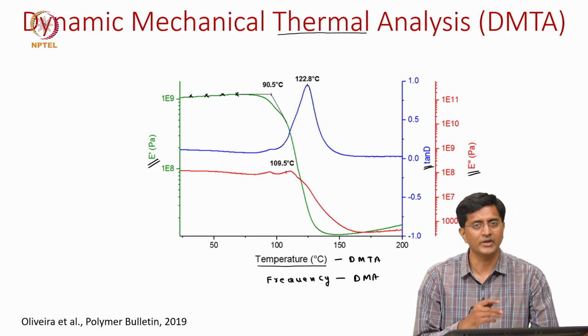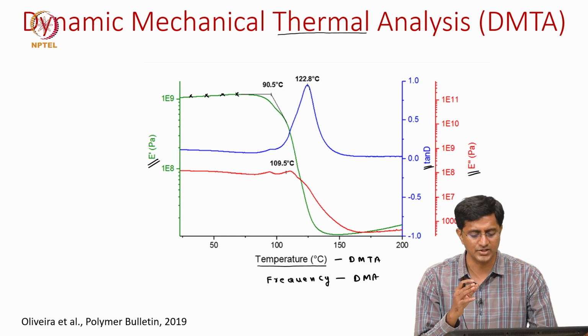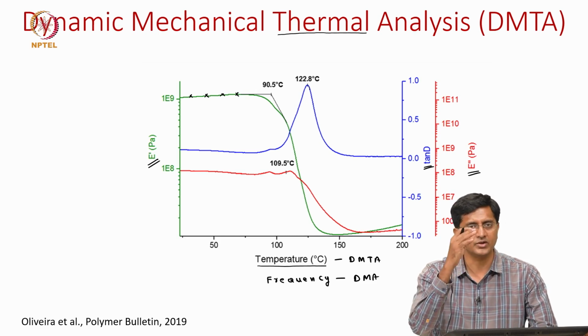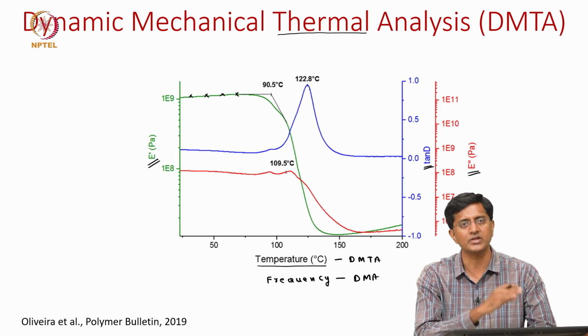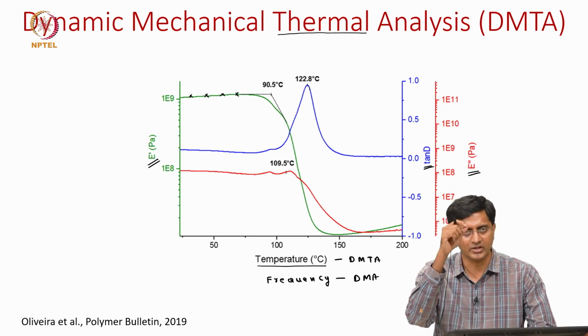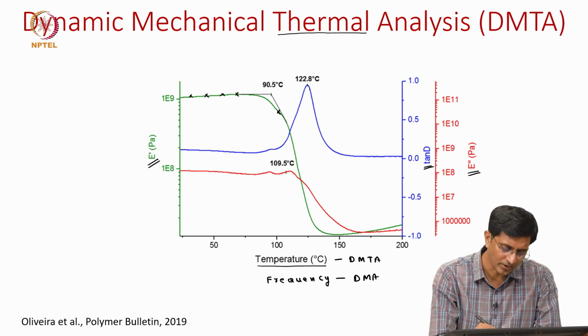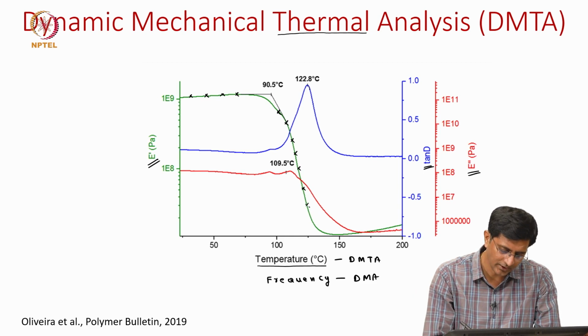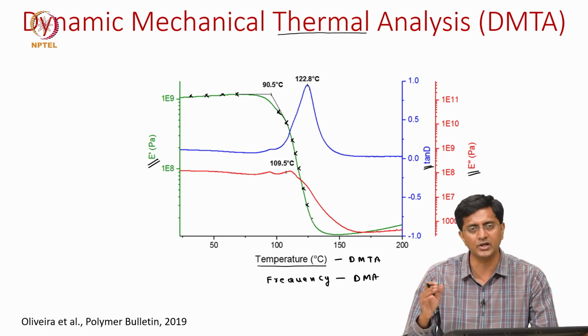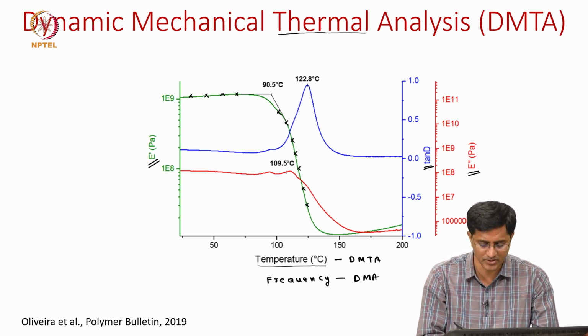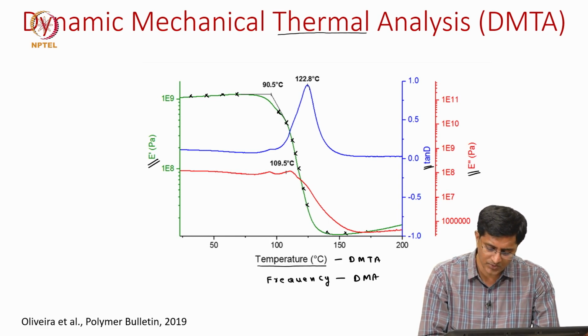But when the temperature reaches the glass transition temperature, we notice that it moves from the glassy phase to the viscoelastic phase, where there is a sharp drop in modulus. So the storage modulus values are decreasing, but once we heat it beyond the glass transition temperature, it becomes more or less constant.